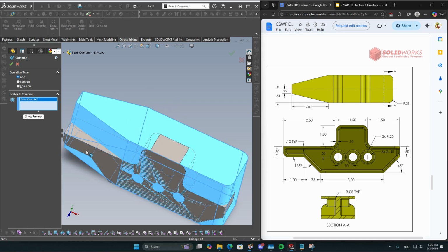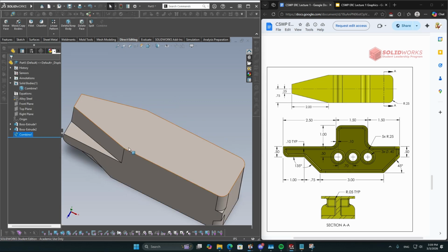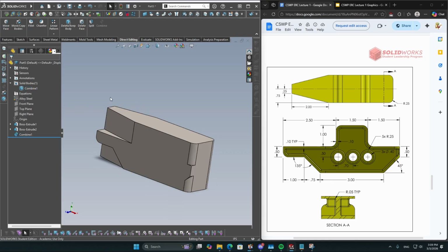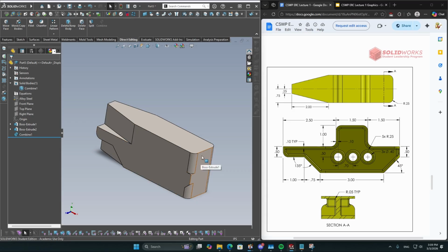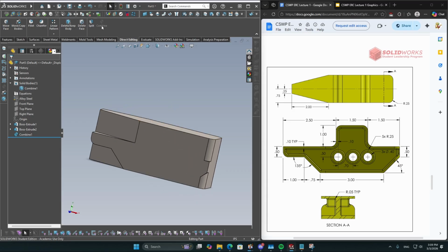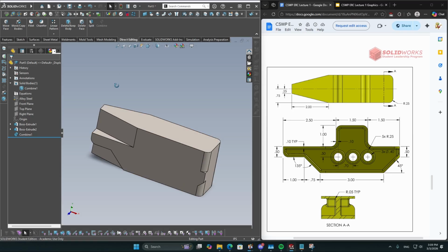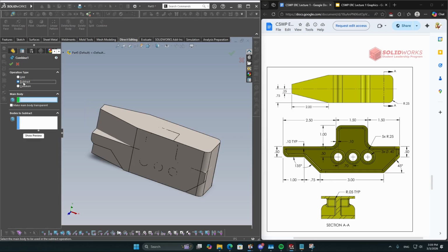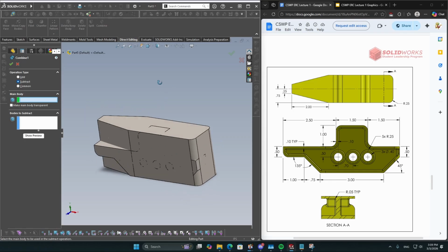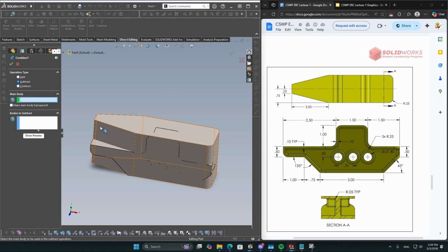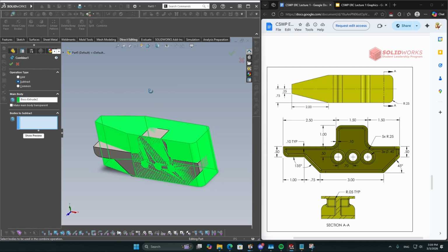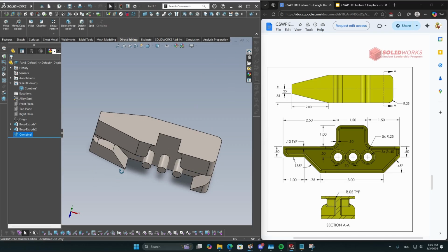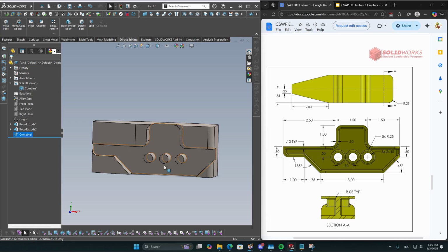So what add does is it takes 2 solid bodies and makes them into one. So you can see it got rid of the portholes, and I now only have 1 solid body. So what does that tell you about combine? Well, you need to have more than 1 solid body for it even to work. You can see it's even grayed out now that I have 1 solid body. So I'm going to go and edit my feature again, and I'm going to now show you subtract. What subtract does is it takes away any area that's in between them. So if I choose, let's say, the second extrusion as my main body, and I subtract the first extrusion, it literally leaves like a hole where it was.